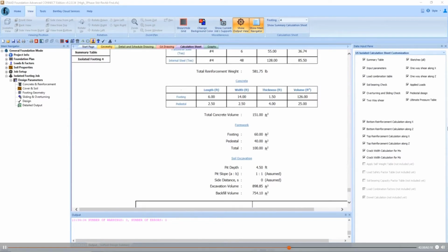And now with the passive pressure, we can actually get a better solution that's more accurate for our different scenarios. There's a couple things that you have to be careful of, and that's a situation where maybe you have excavated a portion of the soil in the direction of the loading.